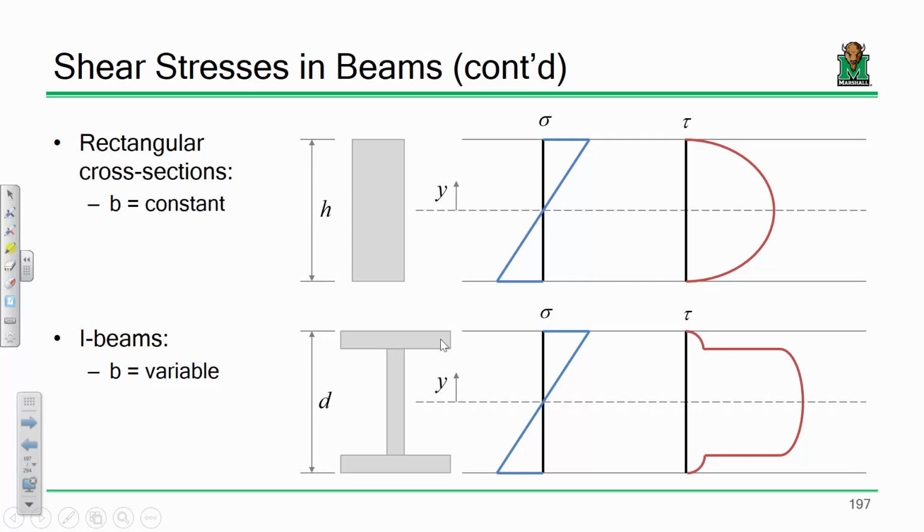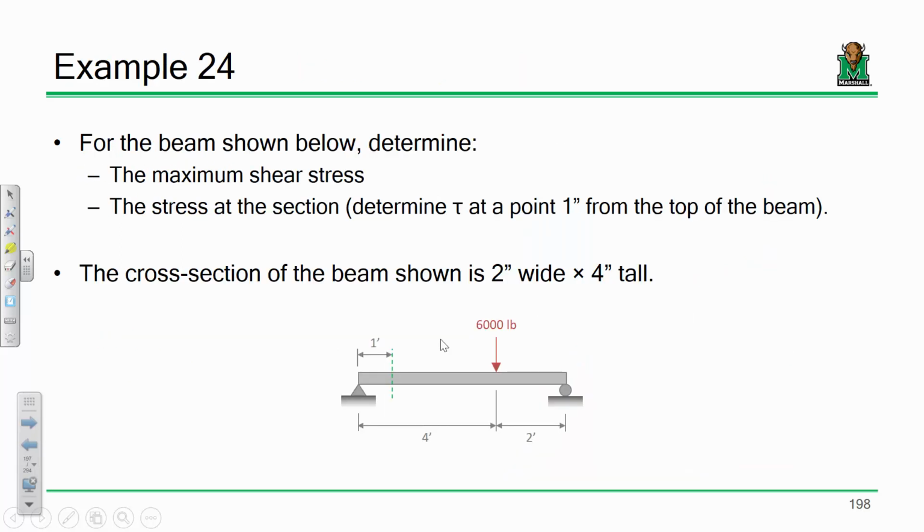transition. In civil engineering, a very common vernacular when thinking about I-beams is that the flanges carry the moment and the web carries the shear. Here's why. At the point where the flange and web meet, you have a sudden jump in shear stress. The flanges hardly see any shear stress at all. As for bending, where do you get most of your moment of inertia from a beam? You get it from having flanges as far away from the centroid as you can. So that's where you get a lot of your bending stress and your bending capacity. Everybody okay with this? Any questions?